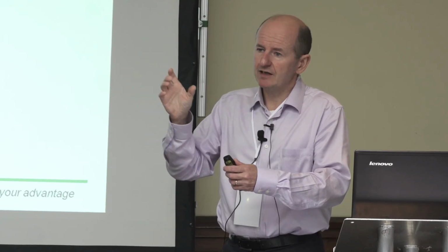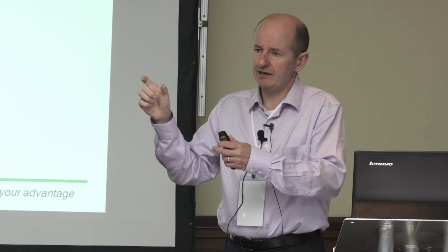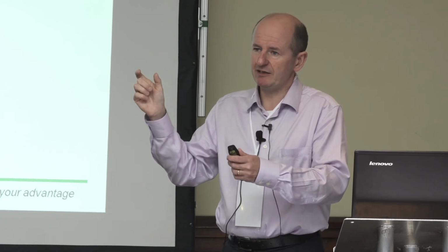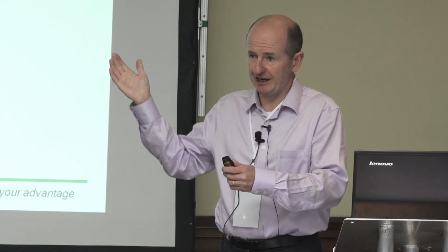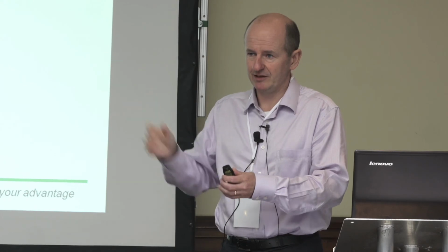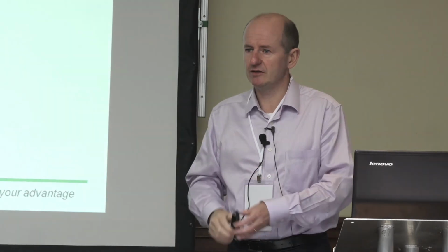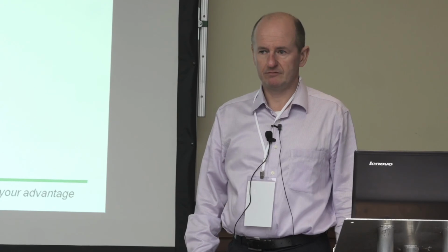And if you've got that 2 milliamps through a 1 kilo ohm resistor, you don't need to be a mathematical genius to work out that it's shifting that bias point around quite a lot. So that's why we try and keep it nice and low. Thanks very much. Okay, Terry.